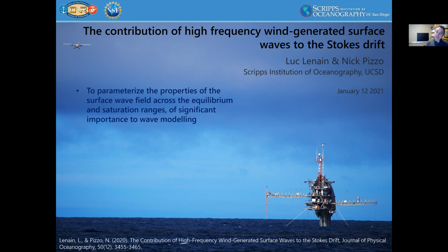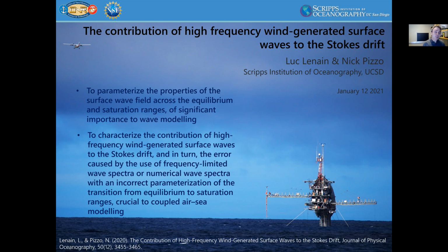And once we have this better depiction of the spectral shape of wind-generated wave, we took it a step further, looking at the Stokes drift, and in particular the contribution of high-frequency wind-generated waves to the Stokes drift, as well as the impact of an incorrect parameterization of this transition to the Stokes drift, because this is of crucial importance to coupled modeling. This is how, through the Stokes drift, you set the boundary condition for those models.